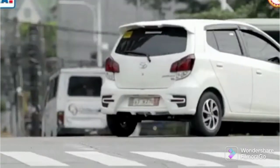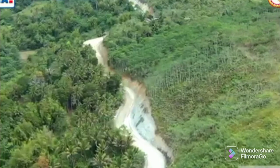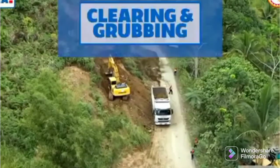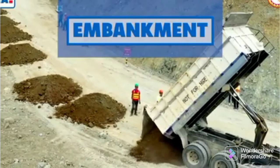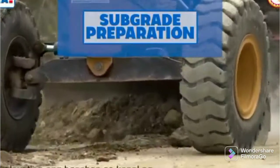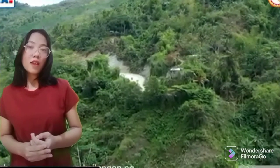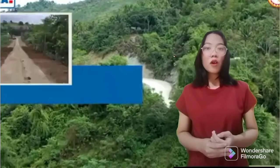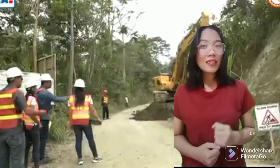Come along to the third step of road construction, which is earthworks. Before roads become concrete and used, there are a lot of processes that it should take. From planning and setting out, here comes the earthworks, which is the clearing and grubbing, excavation, embankment, if needed, or simply transferring or putting the soil, cutting and filling, up until the subgrade preparation of the road. Earthworks depends on the landform, if it's plain, mountainous, or a road already. That's why engineers are very important at these steps.